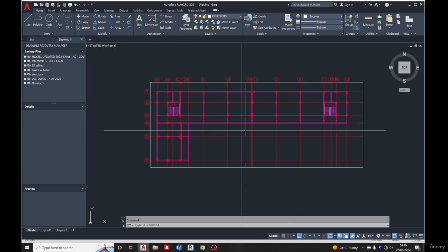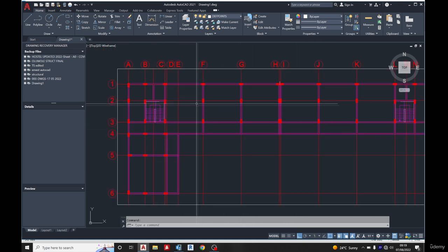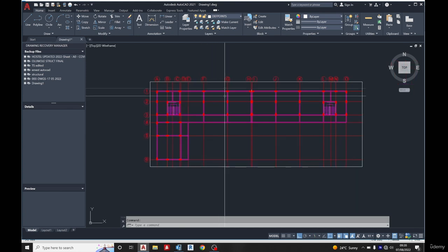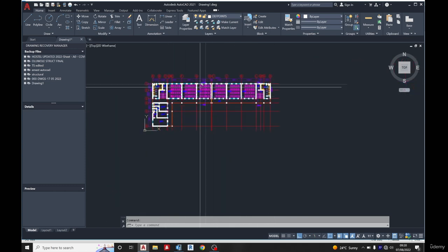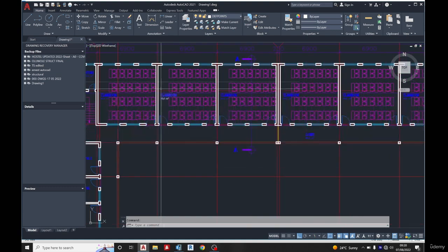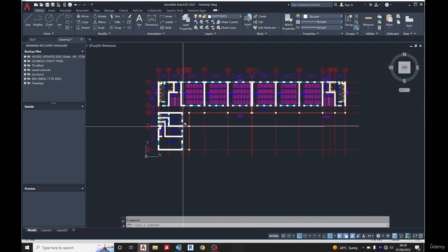But you can see in this case now we need to provide our shear walls at this point, and we need to provide some shear walls at some strategic point inside, because now this place is slender, so the wind is pushing it more like this. So I need to make it more rigid by placing some shear walls at this point. And remember, there is a full wall here without any window, so I can place my shear wall to reduce it at this point. Okay, so that's what I'll be doing.